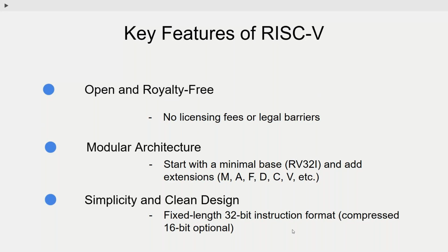This variability in the instruction set hampers my hardware implementation. That is where the RISC-V architecture simplifies things. All the instructions are in 32-bit format. In case of a 32-bit base instruction, if I'm going for 64, that extends to 64-bit. So it simplifies my implementation and my design.